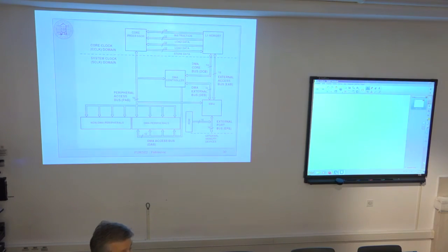So it has several channels. Each of those channels would have a counter, it would have the pointer, and simply it will take the value, write to memory to the pointer value, increment the pointer, and check whether the counter has come to the end. If it did, only then it will generate interrupt request.